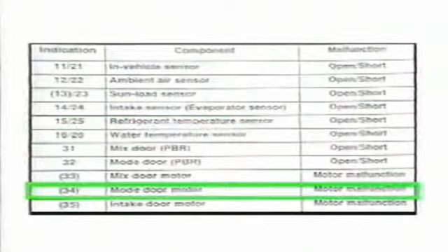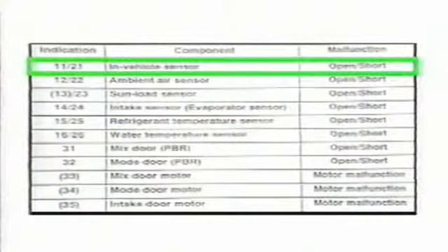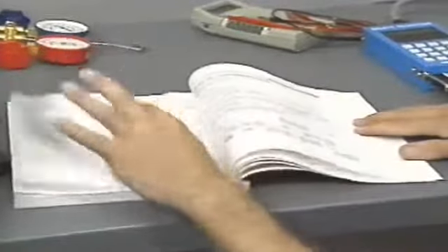Following the bulb and actuator check mode, the system automatically enters the fault code display mode. There are 17 possible fault codes. Any current failure will be displayed as a two-digit code in numerical order. If no codes are present, 00 will be displayed. The service manual describes each of the codes. Remember, diagnostic fault codes can only lead the technician to the general area of the problem.